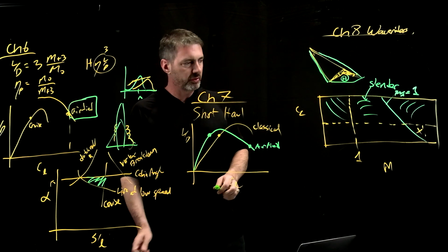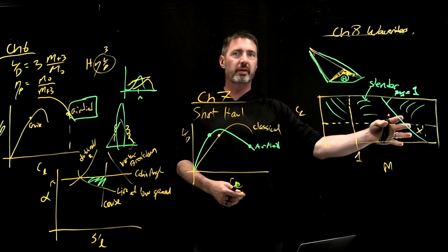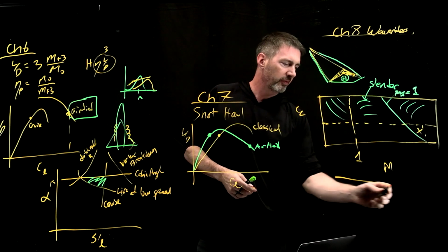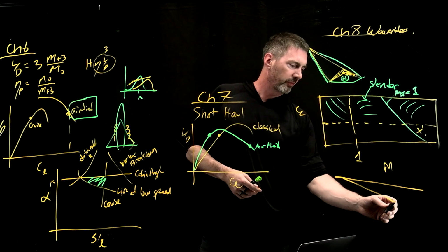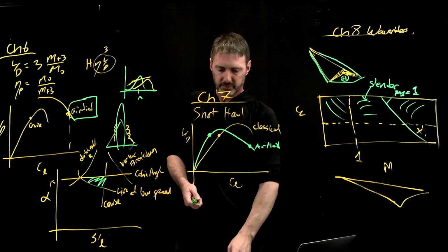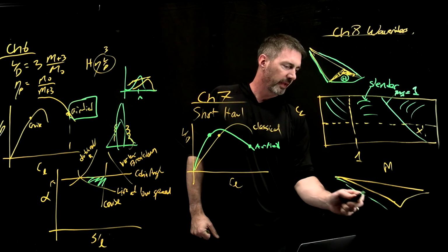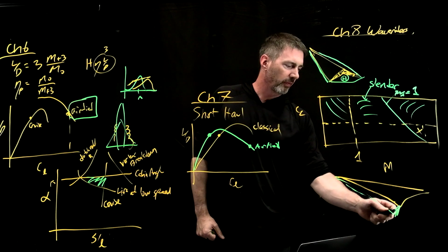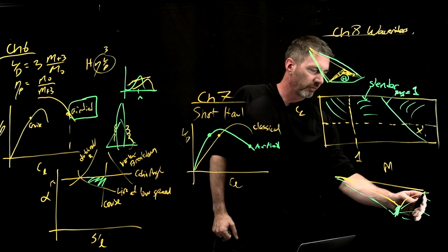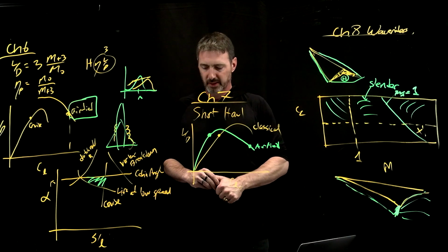And then Kuchemann does talk about propulsion integration, because once you get up to these really high speeds, that's really what it becomes about: can you take your system, if this is your vehicle, and have all of this compression of the air, and then have all your combustion happen at once? That way your combustion is using this as a nozzle. So he talks through that a little bit too.